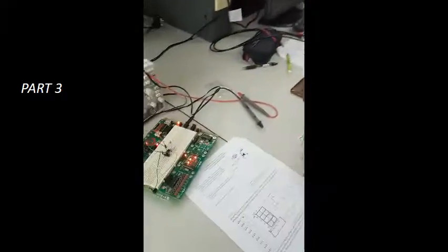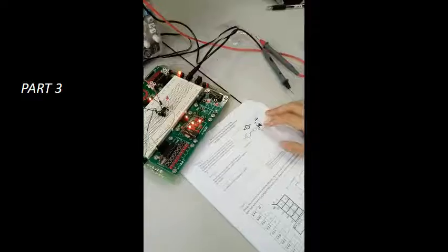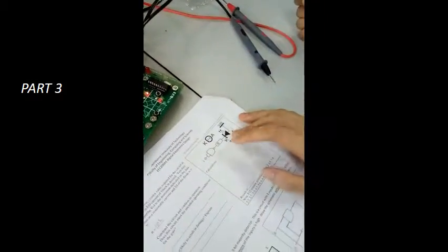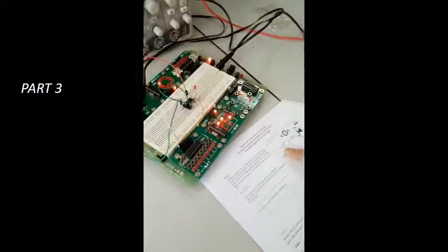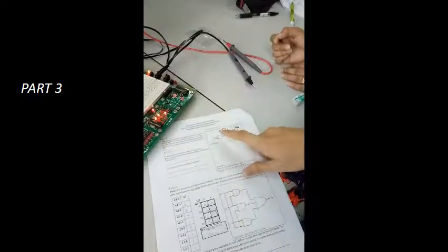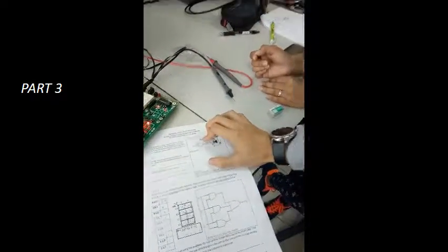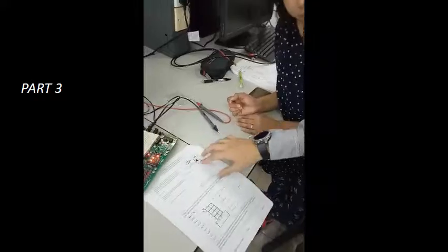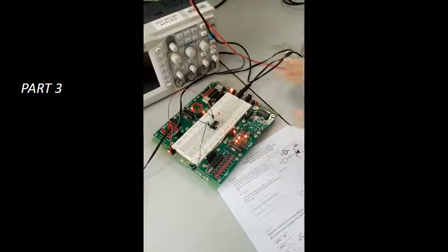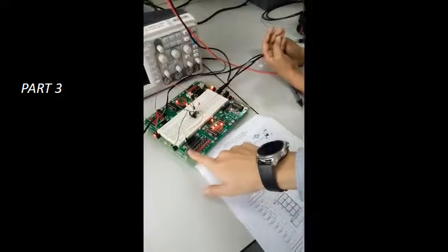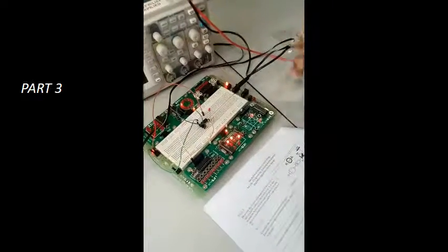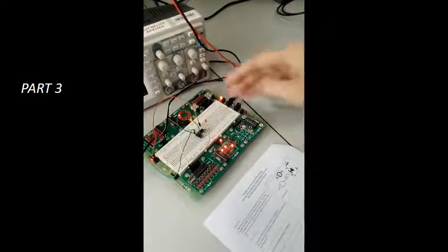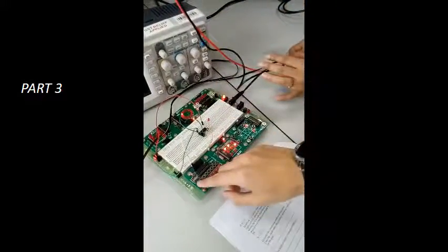This is group 35, part 3. In this experiment, we're proving that the LED only works at a low state. By default, as you can see here, when we're not pressing the button, the input here is at a low state. And since we're using a NAND, it inverts the low state into a high state, which is why the LED, as of now, is not lighting up. But if we do press the button, we convert the input into a high state, which then inverts into a low state, which allows current to flow and the LED will light up.